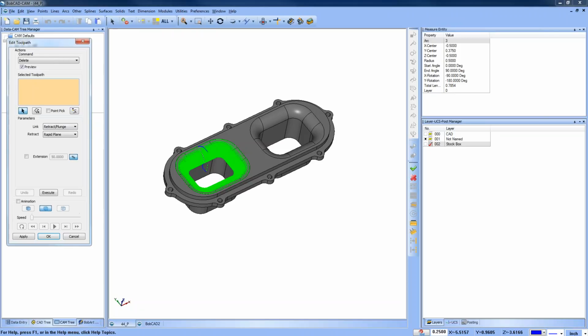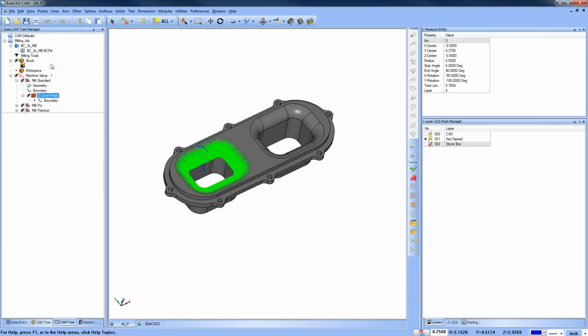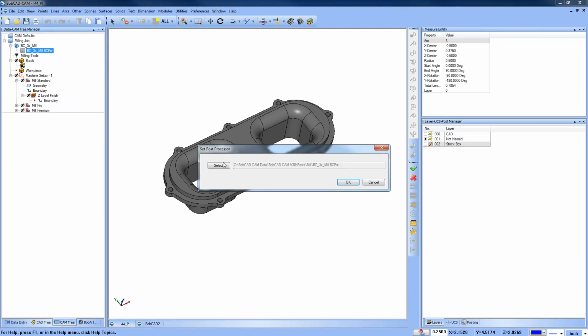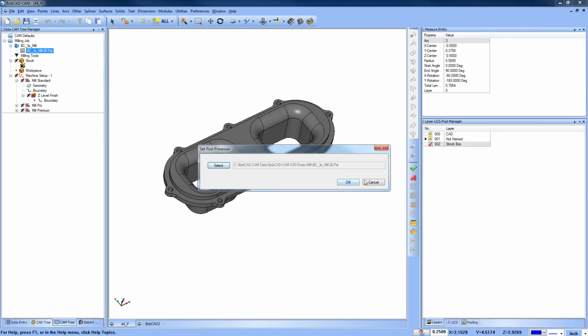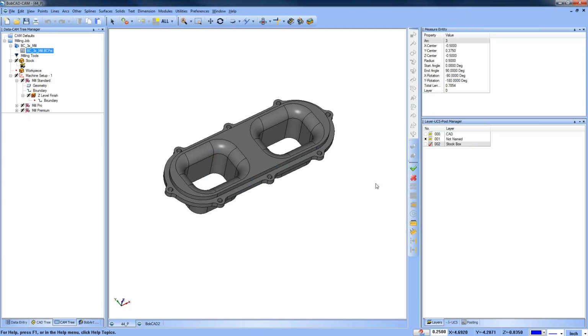Do we need multi-axis Pro post-processor using multi-axis toolpath even in 3-axis machine? No, you do not. You can use your standard post-processor, one of the Haas post-processors, any of the posts that are included with the software, or that you may be running. When you're in 3-axis, it doesn't matter whether you're Mill Pro, Mill Premium, Mill Standard, Mill Express, the post processor will work the same.